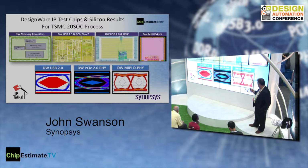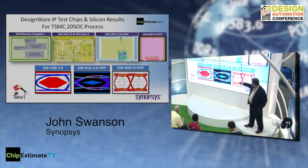Now, I don't know if y'all are familiar with the eye diagrams, but this is really good. You can see there's lots of margins. You've got USB 2, you've got PCI Gen 2, and the MIPI D-PHY. And in every one of them, the eyes here, lots of room, lots of margin. So you're going to get real good signal integrity.